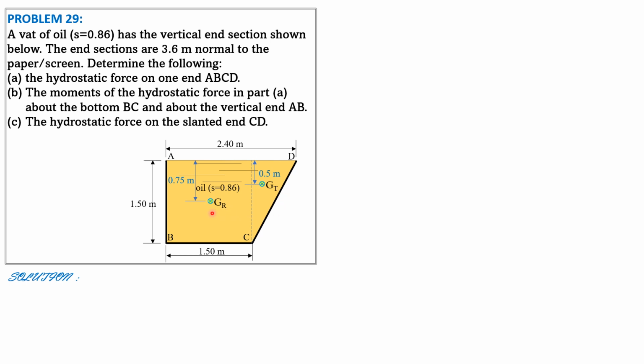Then the location of the forces would be below, at the distance E: this is the center of pressure of the rectangle, and this is the center of pressure of the triangle. If we draw a line through the center of pressure of the triangle and the length is x1, remember that by principle, the hydrostatic force on this triangular section is at the midpoint of x1, or x1 over 2 from either the left or the right.